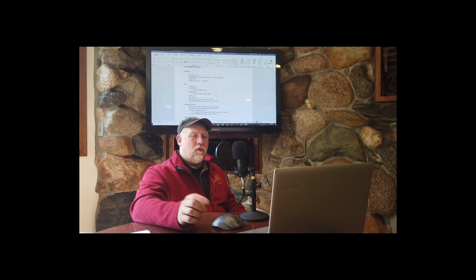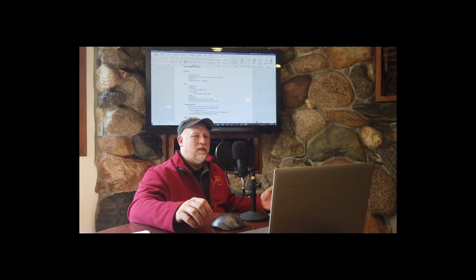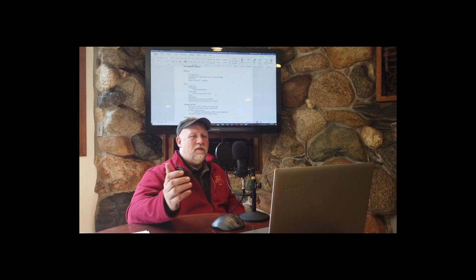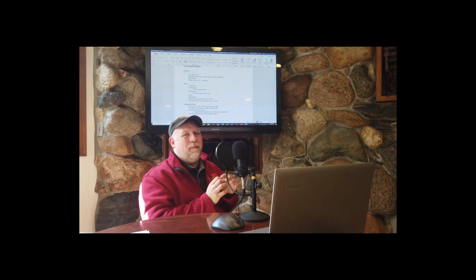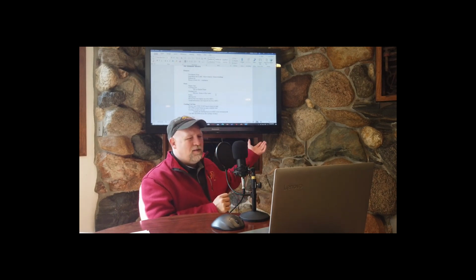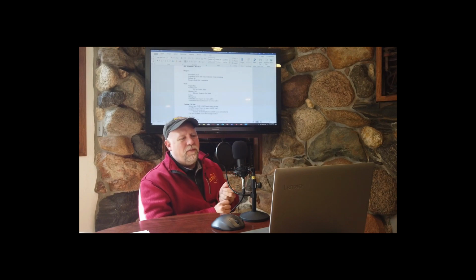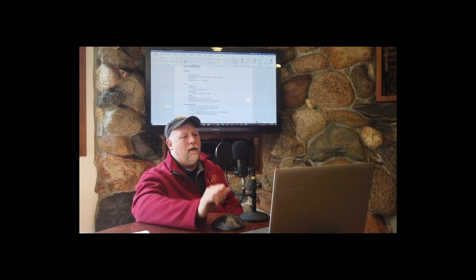Then a mixing box. Remember on the diagram where I drew a picture of the building and I show the outside air, exhaust air, supply air, and return air. That box where all that happens is called the mixing box, where we take return air, we exhaust some of it, we bring in some fresh air from the outside, and we get our mixed air.